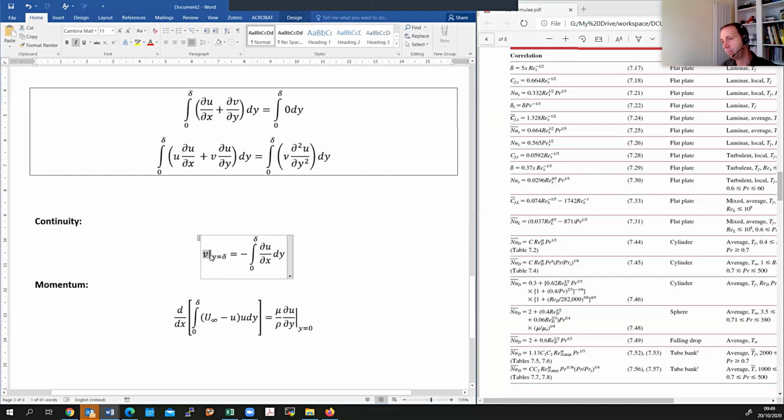So mass conservation tells us that the expansion of the boundary layer in the y direction is what governs that fluid moving upward. The easiest way to look at it is to look at the derivation, so I won't do that and will just say what the physical reason for V to exist is: to dictate that growth of the boundary layer.